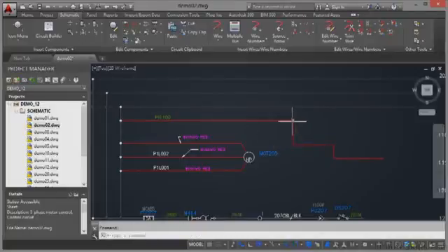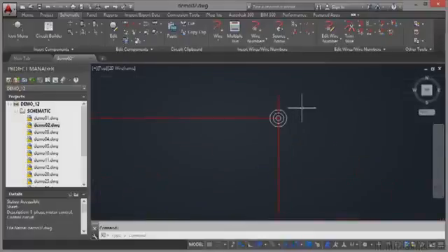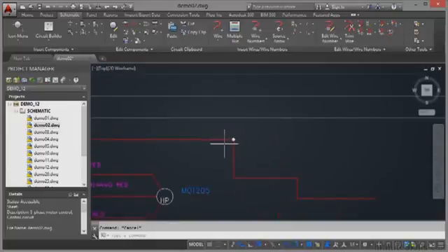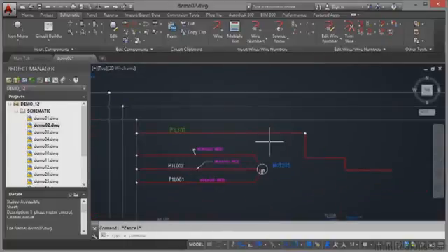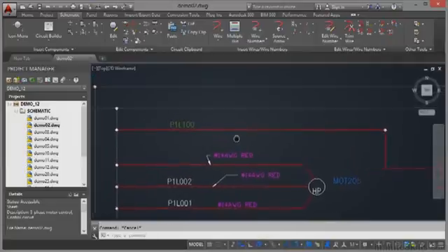Now you will notice, if I zoom in real close, that that wire there needs to come down to the connector. So just click there, click on the grip, take it down to there and click, and it joins to the connector nice and neatly. You can use grips like that all the time on wires. It's a very neat tool. So let's zoom out, pan across, and you can see now that that wire goes right across, and I'm going to zoom in on that wire only.